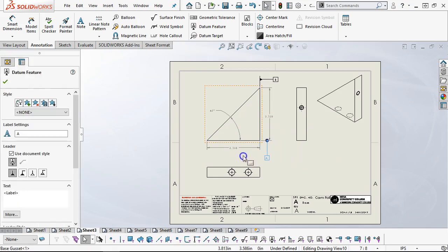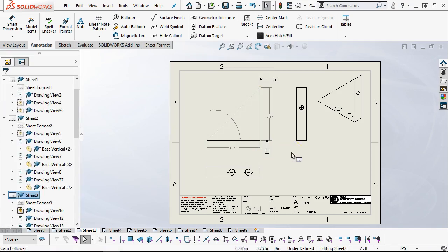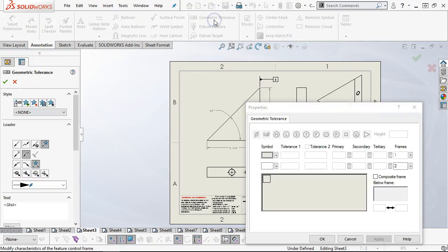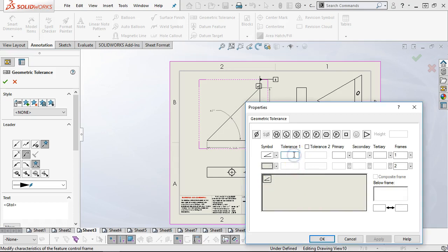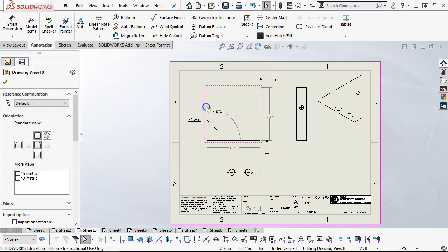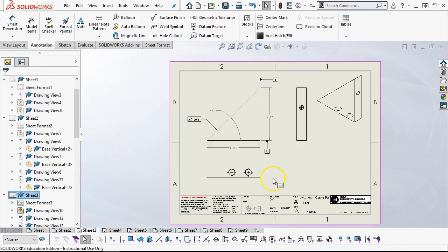Oh, okay, find a spot. There we go. All right, and then to apply the angularity, let's just give it 5,000. So on this end, it doesn't really need angularity. It's more of just an excuse to apply it than anything. So giving it a 5,000th angle zone will more than suffice for the contact. And then the 45 degrees default plus or minus a degree, we should be able to pick that out. Then the position on the two hole locations, those will go through and be under standard tolerances.